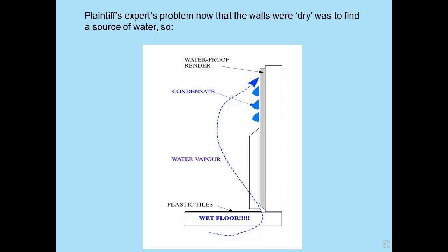However, when one looks at this, it was a self-leveling floor compound with plastic tiles, and there was this tiny gap. Now, the interesting thing was there were water droplets on the plastic tiles. Why? Because that whole area of perimeter of floor was below the dew point.